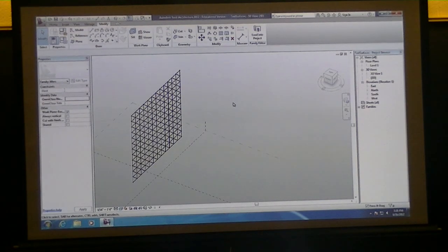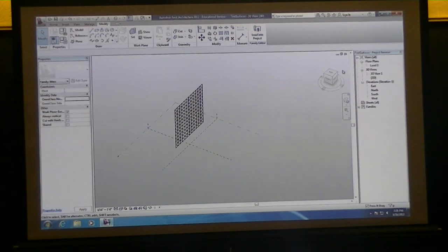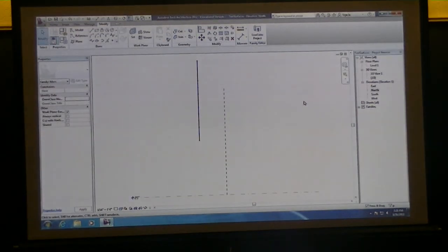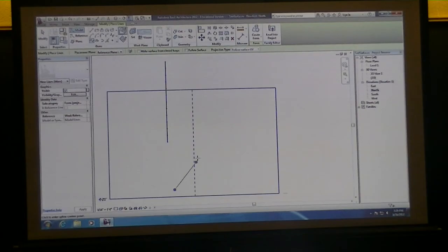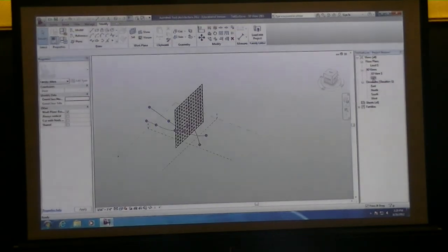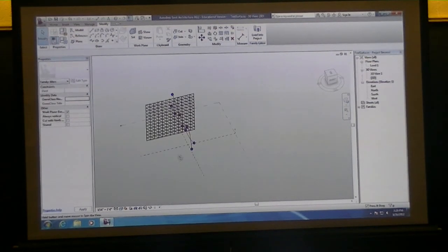All right, while you're in your test surface area, go into an elevation view, maybe a north, doesn't really matter. And I'm just going to make 2 splines. You're in just your test surface file where you've been applying the curtain panel to your straight surface. I just made some splines. I want to make a complex surface.